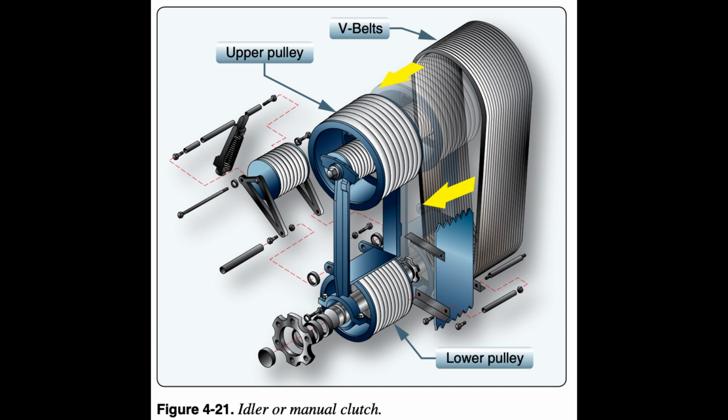As engine speed increases, centrifugal force causes the clutch shoes to move outward and begin sliding against the outer drum. The transmission input shaft begins to rotate, causing the rotor to turn slowly at first, but increasing as the friction increases between the clutch shoes and transmission drum.